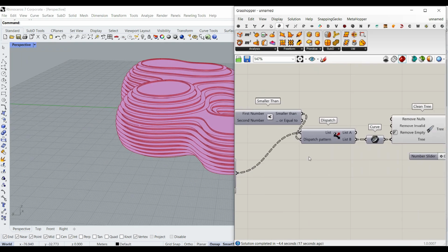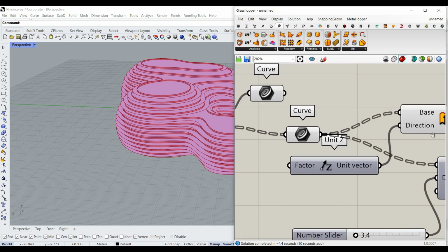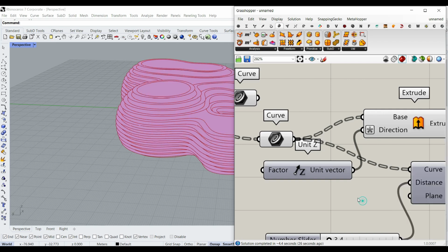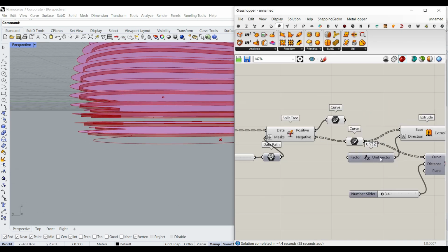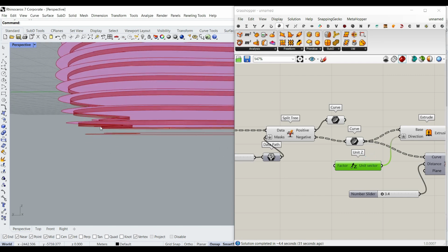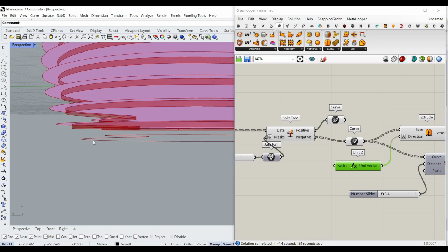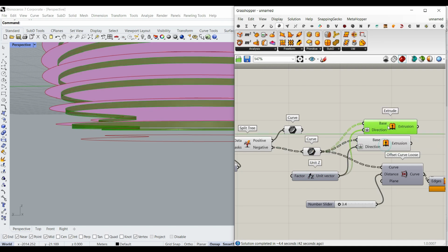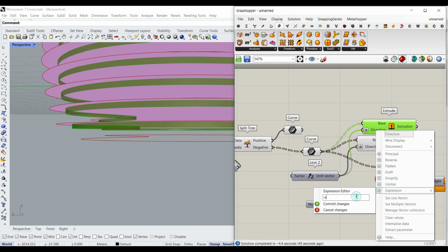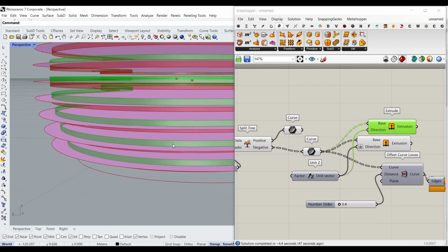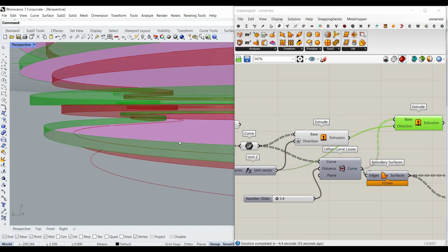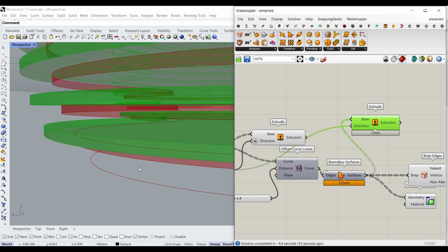You can see how fast it is. It's really cool, and the extrude is really fast. And then we have to give the direction a -x. It's coming down. And how much do we have to give this as the extrusion down? Before I wanted to do that, I also want to extrude this one up as the rooftop, the offset. The offset is going to go up. It's better to extrude the surface so we have a solid.